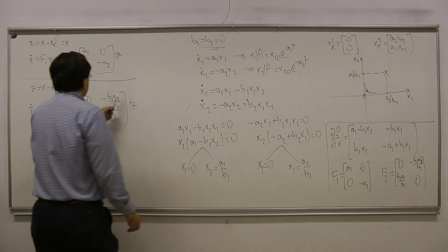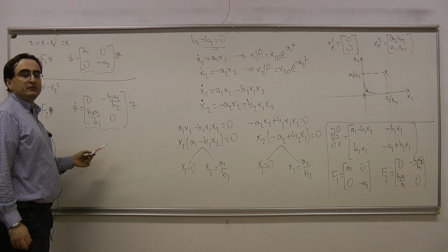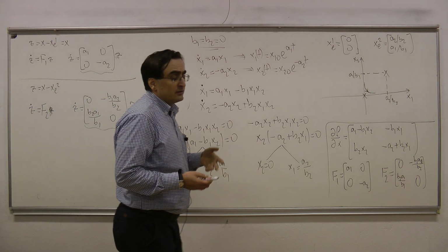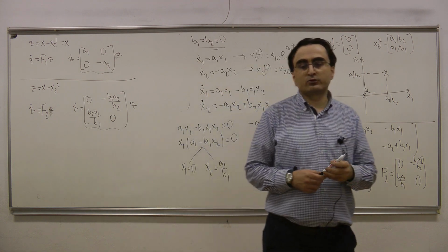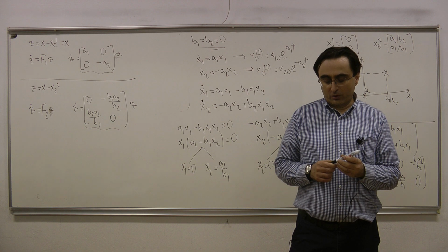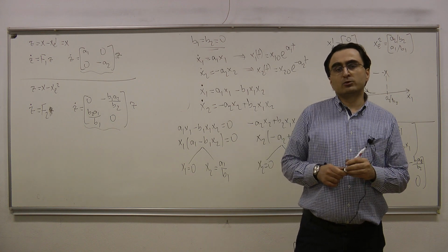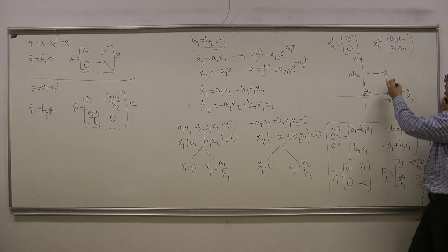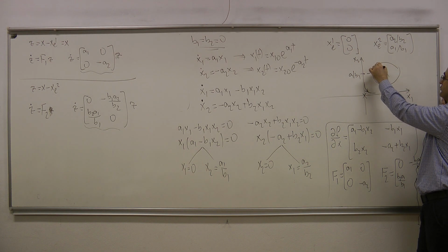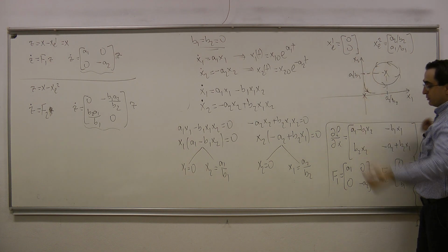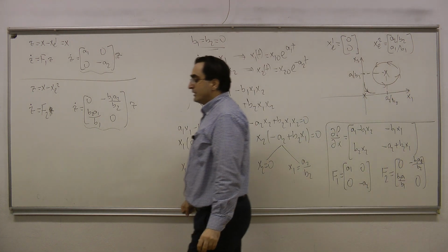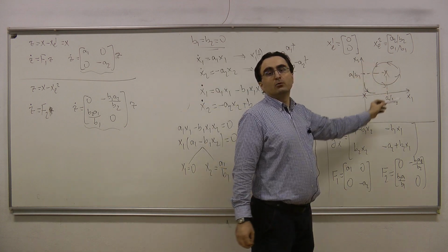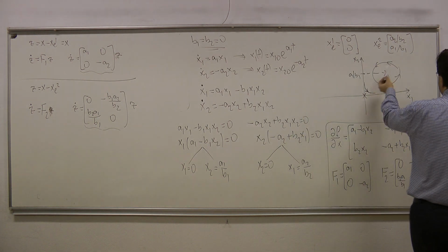On the other hand, when we look at the eigenvalues of this matrix, we are going to see that they are complex. And in this course, just like the course EE404, your third year control theory course, complex eigenvalues mean oscillations. So that means that this system around the second equilibrium point is actually going to oscillate. There are circular or closed trajectories around the equilibrium point where the variables are going to oscillate in a periodic motion. What does this mean?